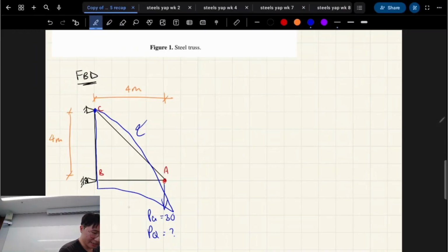And then BC, oh no, not BC, AB is going to want to shrink, right? It's going to want to shrink because it's kind of like pushing in together. So now we've already identified the tension and compression members, just by doing it in your head, step by step. So if you get the wrong answer in your truss analysis, you're going to be like, hold on, this sounds off, alarm bells. I should look at my numbers again and see if I got a sign mixed around or something like that, right?